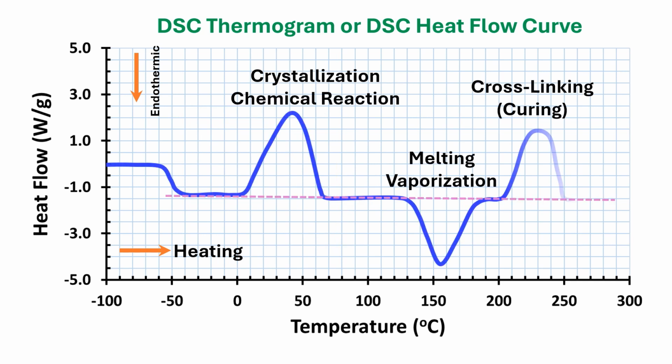Many characteristic changes show an exothermic and endothermic peak. Example of the first, exothermic peak, is crystallization, condensation or chemical reactions in a sample. Example of the second, endothermic peak, is melting, vaporization, gelatinization.